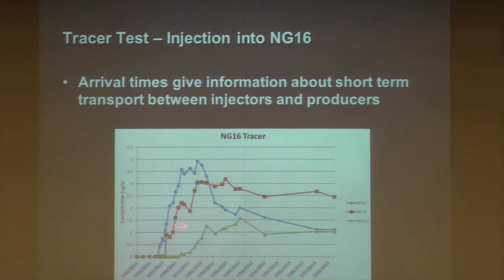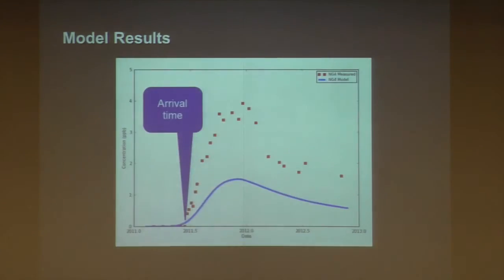I should point out that we are getting recycling of tracers, so you inject the slug of tracer into your well, that then goes back to your production wells, it comes back in the injected fluid again and is recycled. So you get recycling with the tracer, and this tail that we're seeing here is about 1 part per billion. It's the recycled tracer just going back through the injection fluid again.